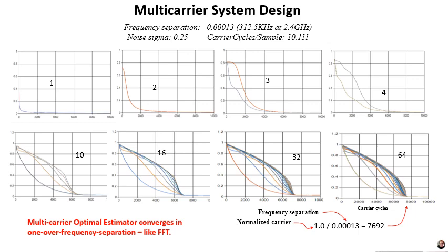This phenomenon continues as new subcarriers are added in pairs, with the first 2 of the lower frequency converging much faster than the higher frequency carriers. The 64 carrier case is of most interest because of its relationship to 802.11. From 10 carriers to 64 carriers shown on the bottom row of graphs, the estimate sigma time histories all converge to a point on the time or cycles axis.